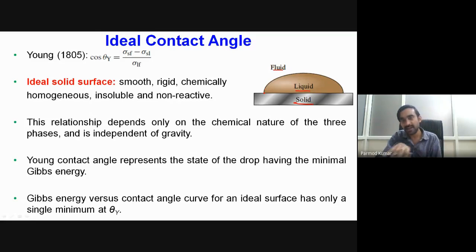In the two-dimensional view it is a contact point, but in actual practice we have a three-dimensional liquid droplet. Because of the three-dimensional nature of the droplet, we have the existence of a contact line. Okay, so this is one central plane of that three-dimensional picture. Over here there comes one very important concept, which is referred to as contact angle. Okay, so what is contact angle? It is if we take the tangent to the liquid-fluid interface and the tangent to the solid-liquid interface, and we take these tangents at our contact line.